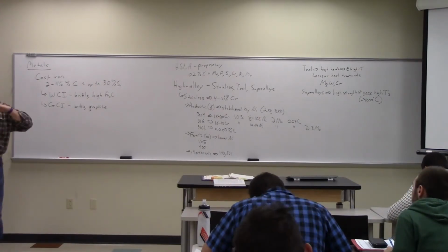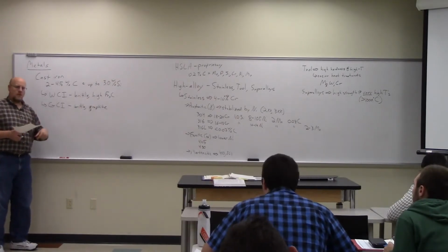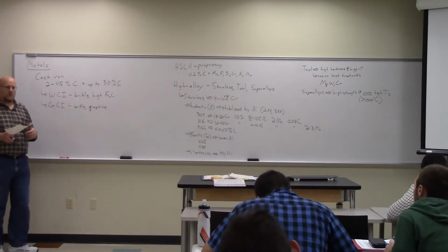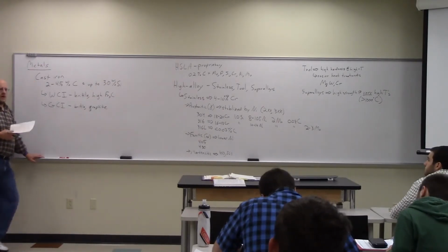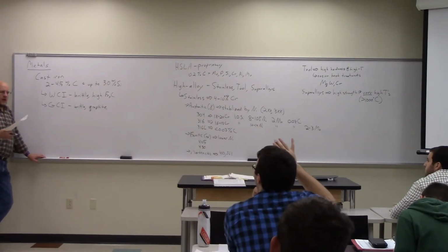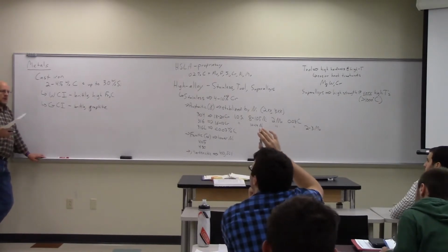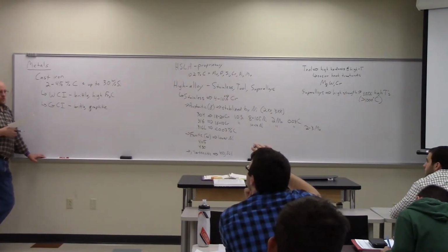The fracture surface looks more gray than white. So white cast iron is actually white? It appears white. I mean, it looks metallic when I crack it, right? It's shiny. And so it's white. Whereas the gray cast iron, imagine taking that shiny thing and then sprinkling it with graphite dust, it would look gray. So the gray cast iron, when you break it, looks gray.